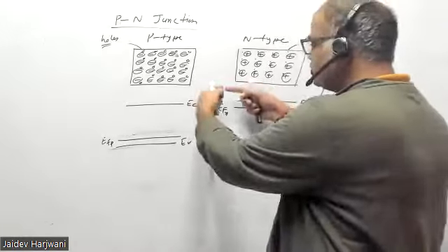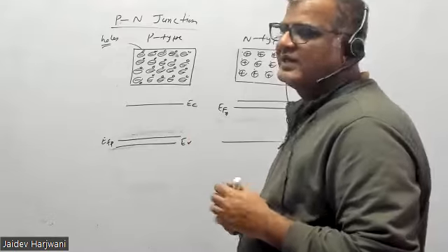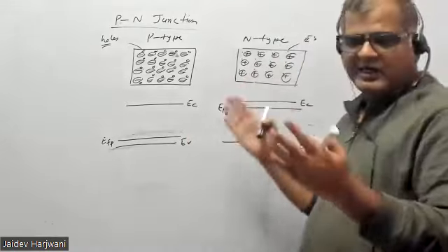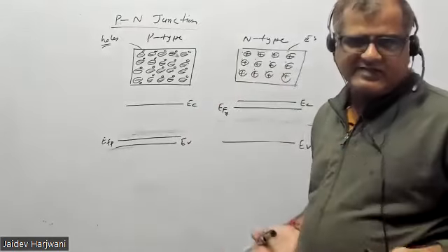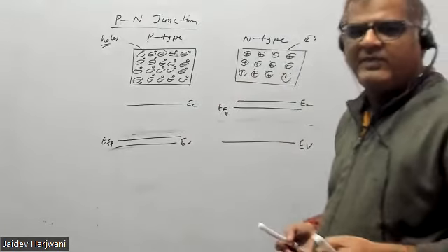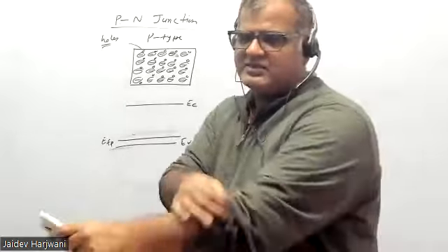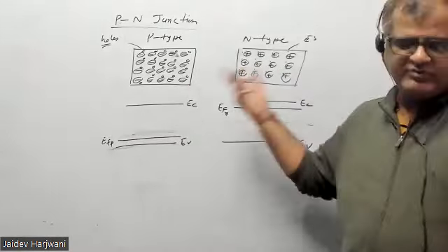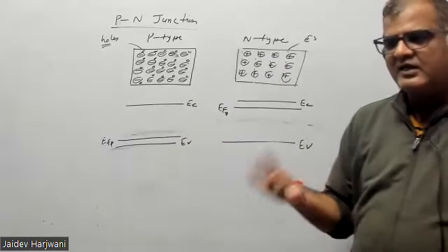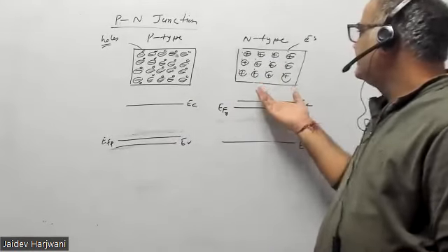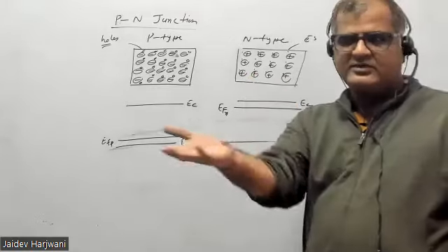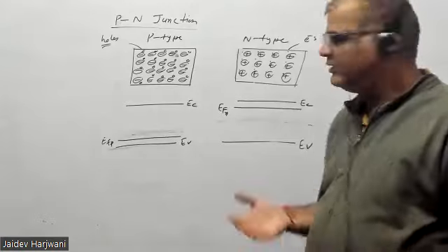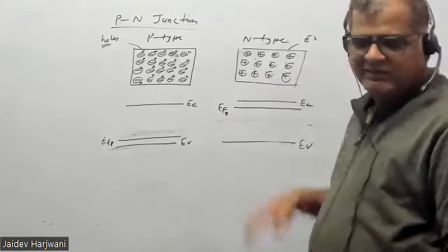Now, when I say that to make a PN junction we take an n-type and a p-type material and join them, actually that doesn't happen like this in a practical situation. Whenever you are making a device, there are methods by which you form the junction. Ideally, people take an ideal silicon crystal and dope n-type impurity inside it, so it becomes n-type material.